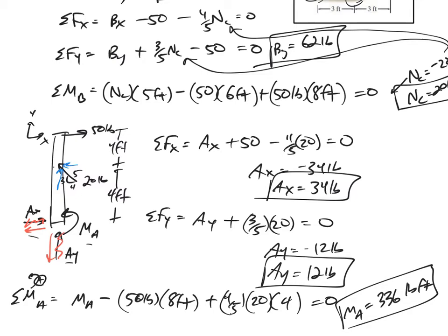All right, that's just one type of frames and machines problem. The one on the test will probably not be exactly like that. Look at some of the other ones. Look at ones where everything had 4 unknowns, and so you had to draw the free body diagram and the equations for one, draw the free body diagram and the equations for the other one, and solve for all of those. So look at all the different things you could do. Look at distributed loads. I could put a distributed load on there. Make sure you can handle those too. Okay?